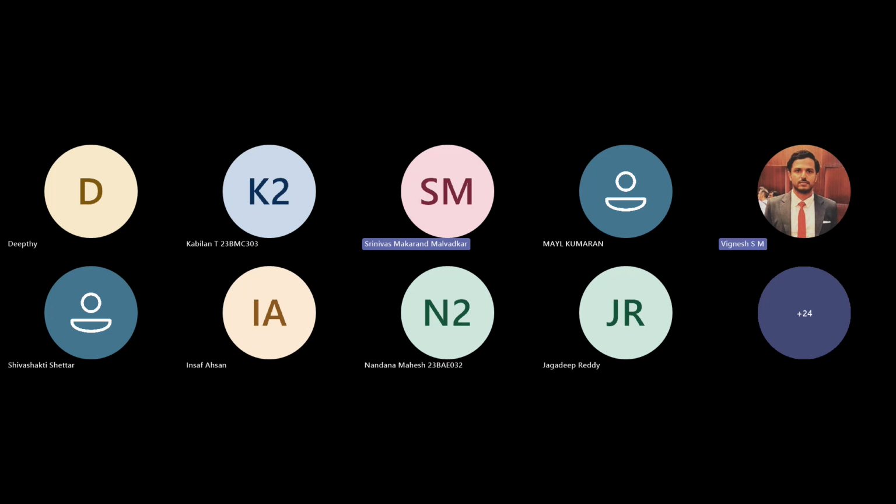Yes, I will recommend doing a grid independence study, as I discussed. For example, let's say you have done a simulation of 2 million, then do it for 2.5, then 3, 3.5, 4. You need to look at the result. Let's imagine I'm looking at the lift or thrust force acting on the quadcopter.